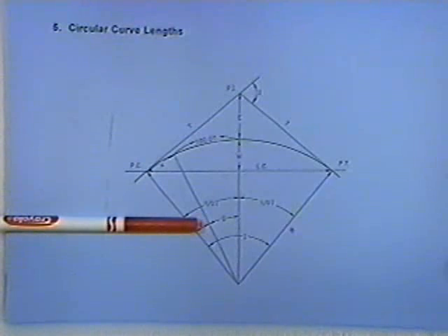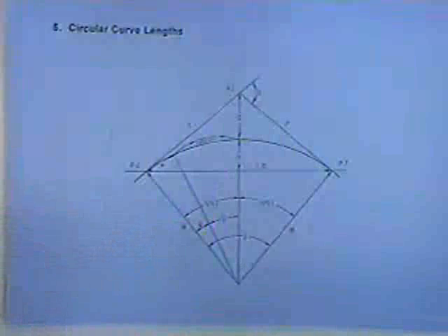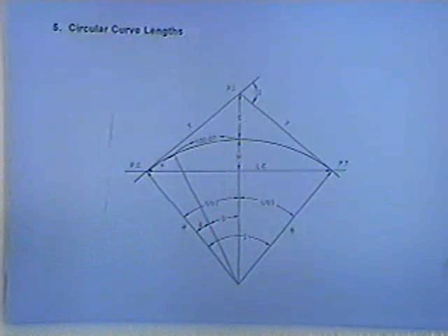Typically, for a certain speed, we'll look up in a table a degree of curve that we can use for that speed. And that degree of curve is defined as what degree of curve for that 100-foot distance of circular arc that we have at the top of that drawing. So we have these definitions, the arc definition and the chord definition, but the more common is the chord definition. Okay, so we've got degree of curve. You'll also notice radius for that particular curve, and we'll work a problem in just a minute where we look at some of those things.